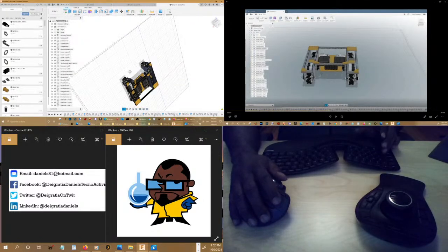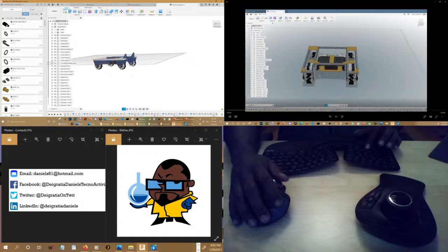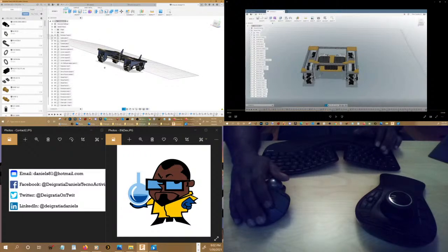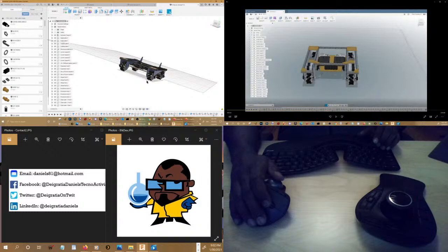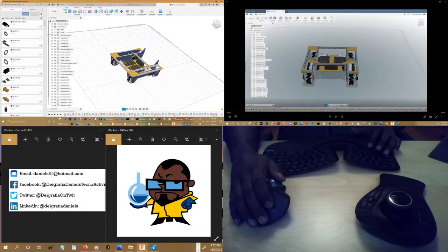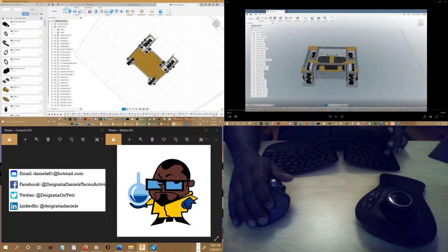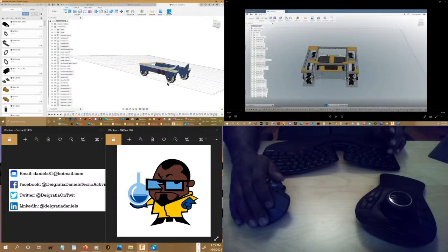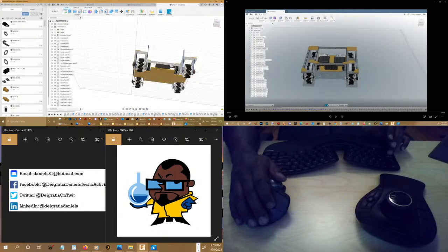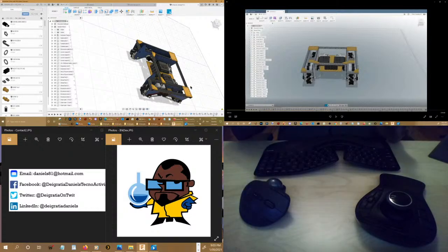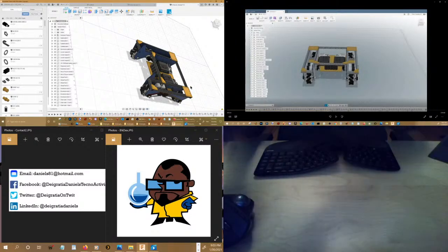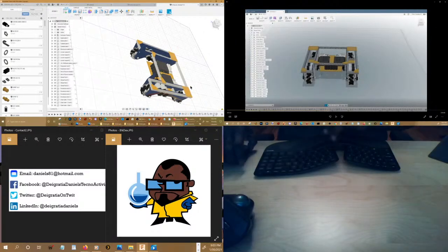I'm on orbit. I am pushing shift, and none of them changed. Oh gosh, I don't know what that is. I'm pushing my middle mouse button. So my middle mouse button seems to be the view control. I'm pushing shift, which allows me to go from pan to orbit. So this is the way 3D modelers will work without a space mouse.